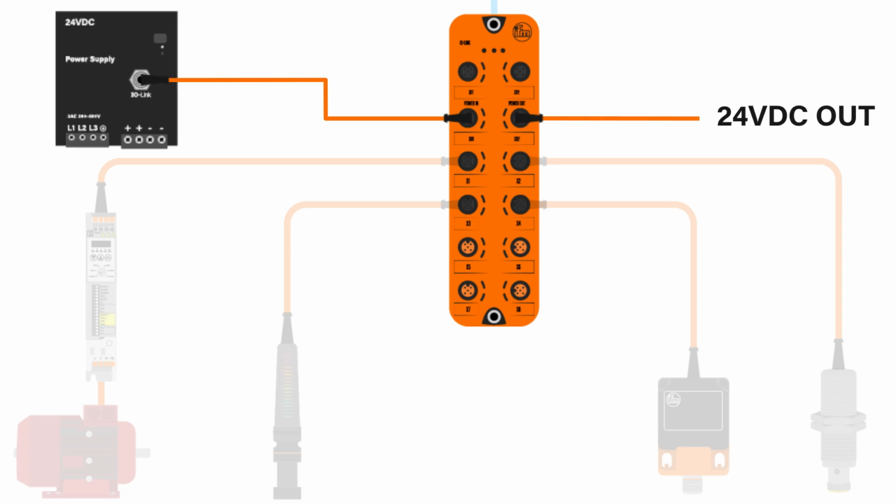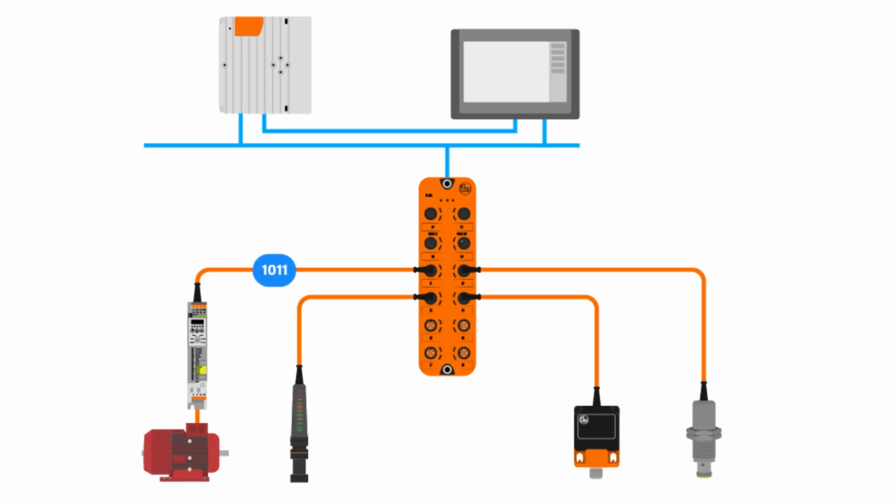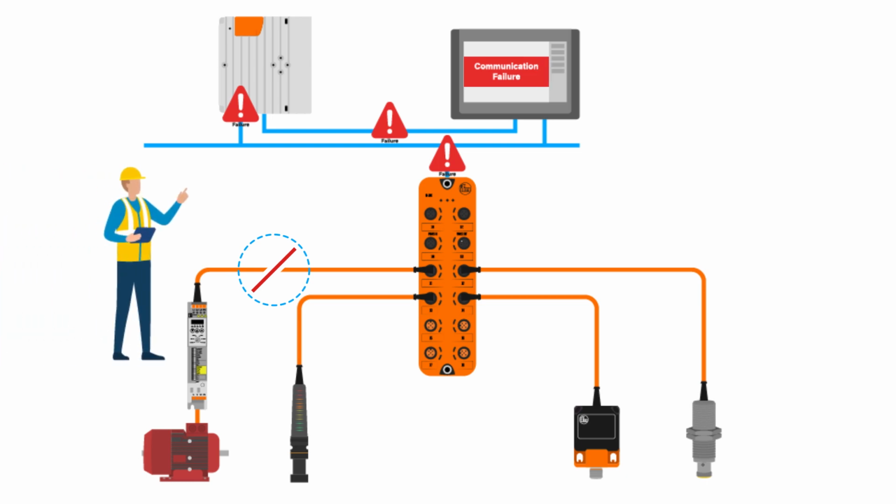IO-Link is a very robust communication system that operates using 24 volts. Transmission errors can occur for a number of reasons. In general, a cable fault or a power surge can temporarily interfere with transmissions. If an error is detected, the message attempts transmission up to an additional 2 times. Only after the transmission has failed for a 3rd time does the IO-Link master recognize a communication failure. Upon recognizing this, the IO-Link master will signal the communications failure to the higher level controller. This can then alert operators or maintenance staff of the issue so they can physically attend to and rectify the problem.